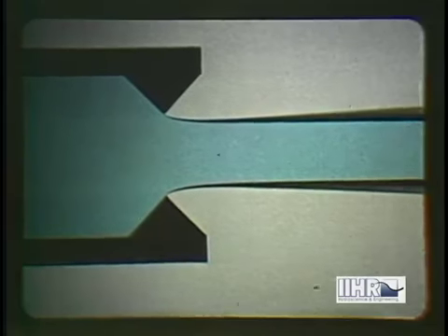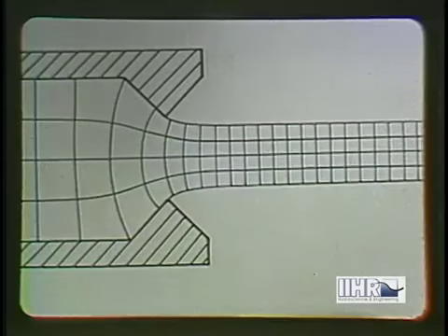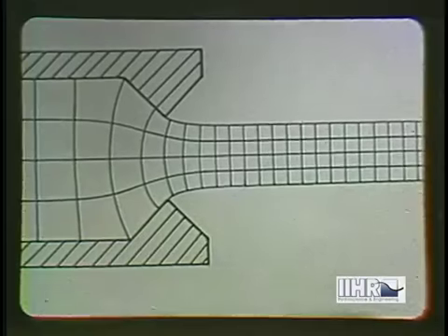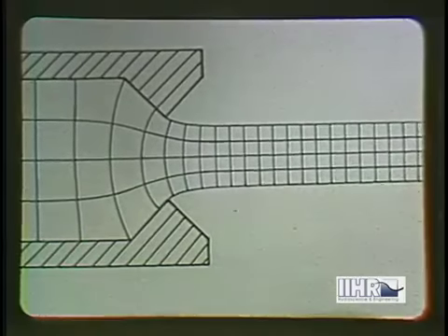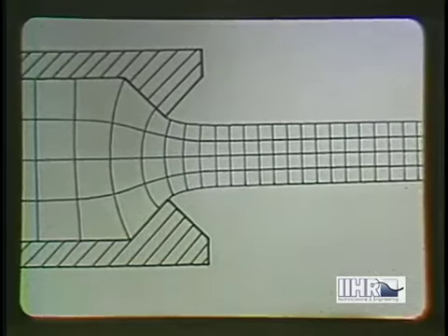Instead, the flow separates from the boundary, and the mean surface of separation tends to assume a curvature which is compatible with the requirement of constant pressure along it. The formation of secondary eddies in the separation zone is eliminated in the case of a liquid jet in contact with the atmosphere. The shape of such a jet beyond the point of separation from the boundary can now be predicted from an analysis related to the flow net, and orifices and nozzles thus become useful flow meters once the degree of jet contraction, and thence the Euler number, has been determined.